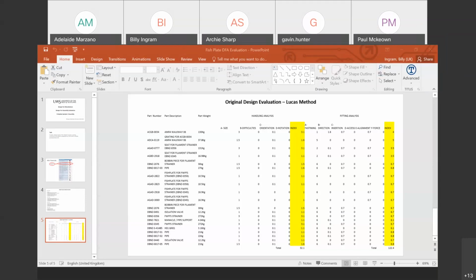So then there's no real loss of material or wastage from the green material. You're building one part number to size, and then using the shim plate to lift up and take out any tolerance in there or build errors. Then you'd be able to assemble it at ship first time by lining up the holes rather than having to walk up and down the ship to machine it, take it back up, offer it up, take it back down, machine again, and do it that way.